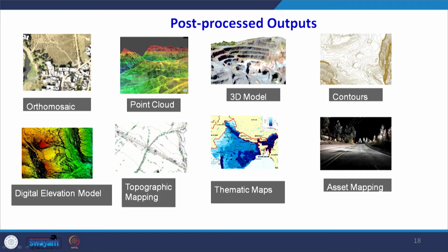of this data set. Now post processing of the data is also very important, because the accuracy at the end would depend upon how well we are post processing the data. The raw data which we are collecting might have certain errors. We have to remove those errors, apply corrections to the data, and remove some of the artificial points which have been generated while scanning the whole area.